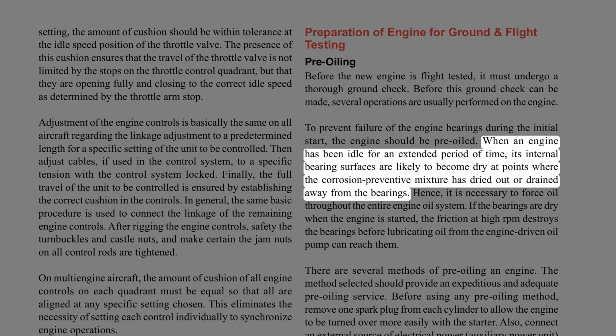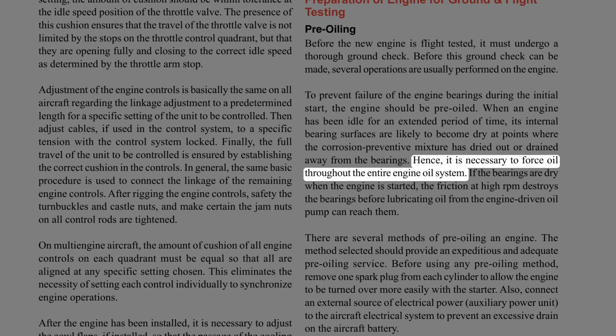When an engine has been idle for an extended period of time, its internal bearing surfaces are likely to become dry at points where the corrosion-preventive mixture has dried out or drained away from the bearings. Hence, it is necessary to force oil throughout the entire engine oil system.